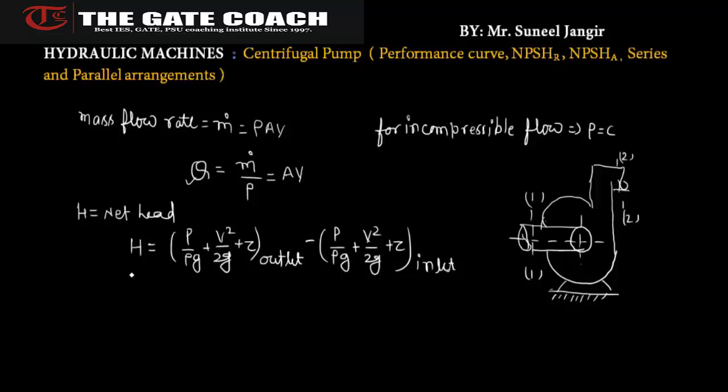What does that mean? If I write the useful power, it is not rho Q; it is the specific weight of the fluid times the discharge times the head.